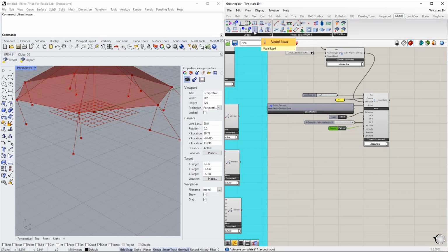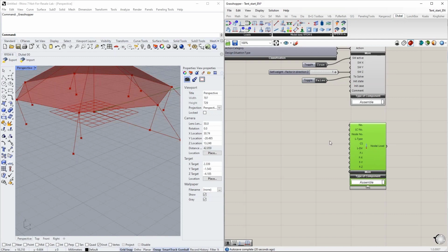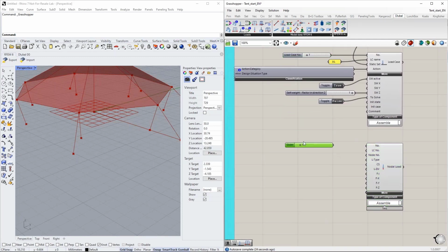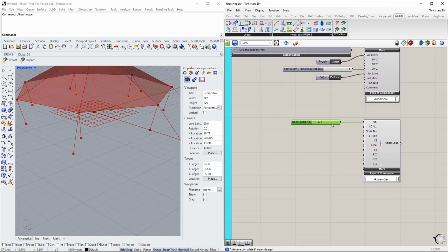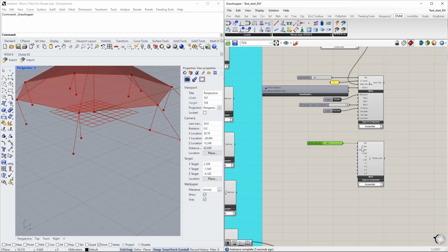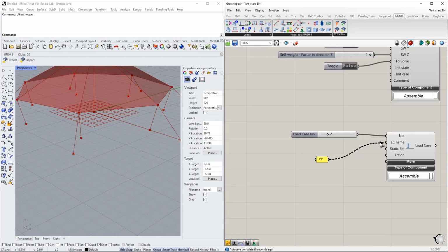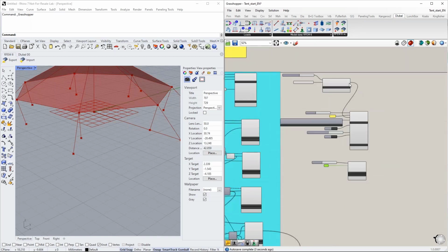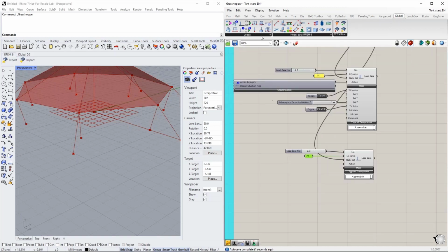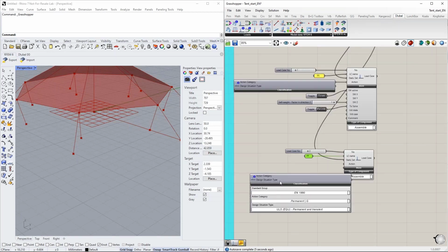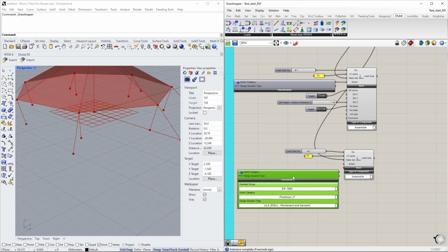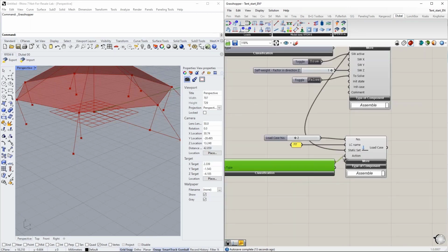Okay, second load case. We have 3 in general, so it will not take much longer. I can copy here my index number list slider, actually, then the load case. Oh, sorry, wrong component, my bad. I want to create a different load case. Index number is number 2. The name could be form finding, in short. And then the static analysis setting is again this one here. Action category is then in 1990, pre-stress. Pre-stress is the action category that we use for, let's say, the form finding. I connect it to it, and then I'm done.